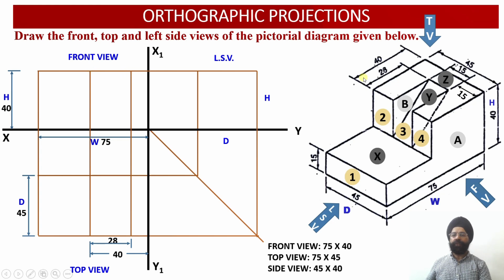That is the end of my element number 1. From the end of my element number 1, I am going to move 28 millimeter backwards towards the rightmost edge over there. This is going to be my rightmost edge, so that the remaining thickness will become 12 millimeter.